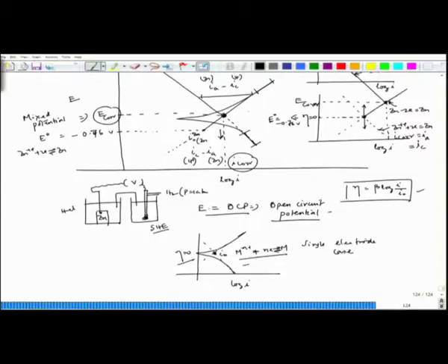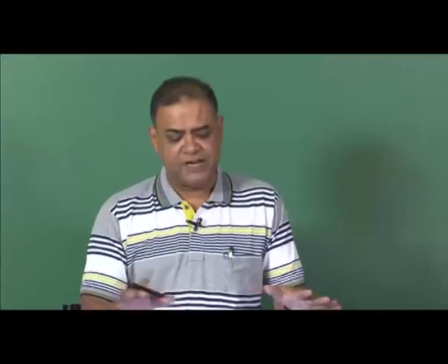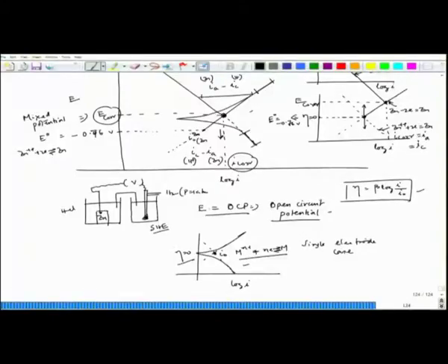This particular part will come in corrosion part 2, but since we have considered this, we are just explaining a little bit. If I look at the mixed potential theory in a nutshell, we could see that the new potential is achieved due to the polarization of those partial reactions. One would definitely be cathodic and another one definitely anodic polarization, in this simple situation where the entire reaction is divided into two parts.